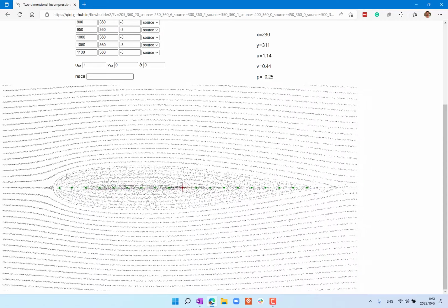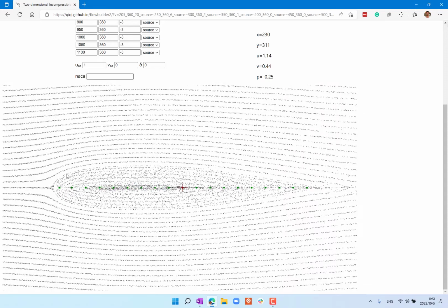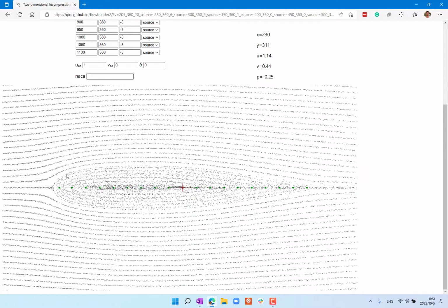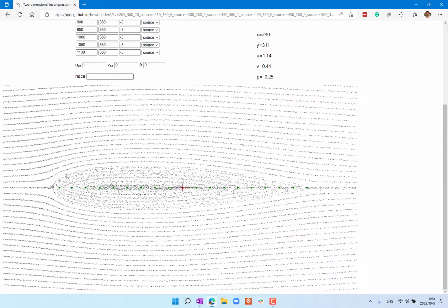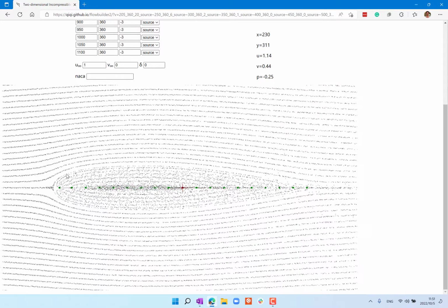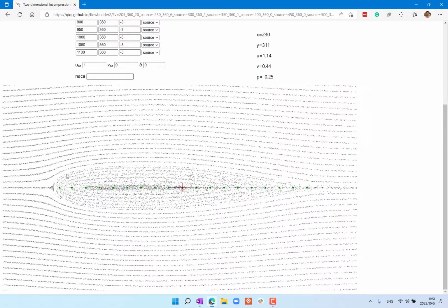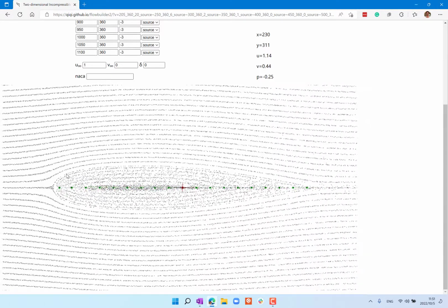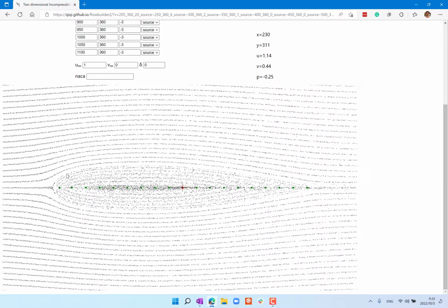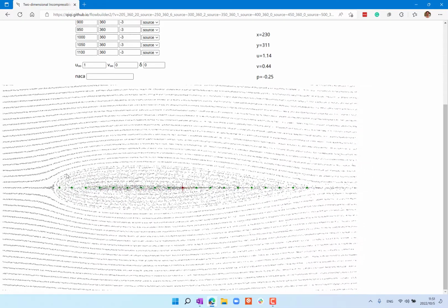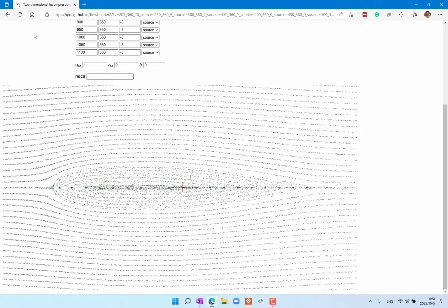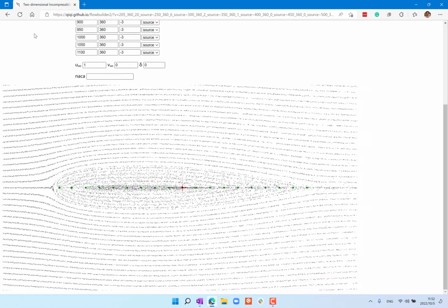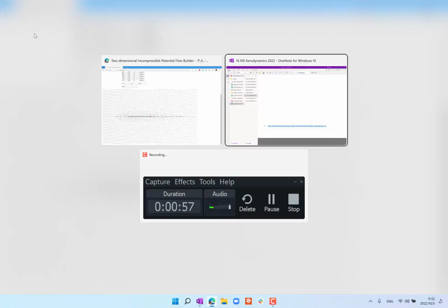Okay, so this is symmetric airfoils, and we don't really care about symmetric airfoils at zero angle of attack because it doesn't really generate any lift, right? So what we really care about is either asymmetric airfoils with a camber or symmetric airfoils at non-zero angle of attack because these generate lift. But the placement of sources and sinks is a very good exercise because in order to get non-symmetric airfoils, we need vortices, and placing vortices is slightly more complex than placing sources.